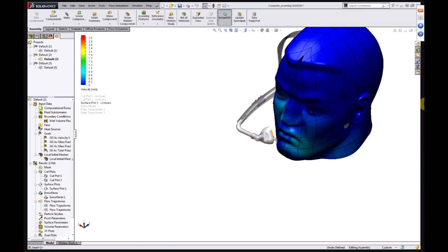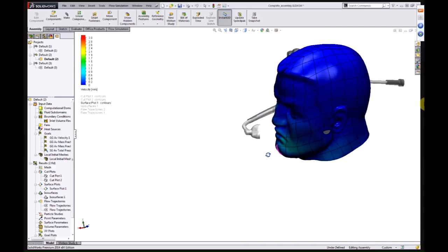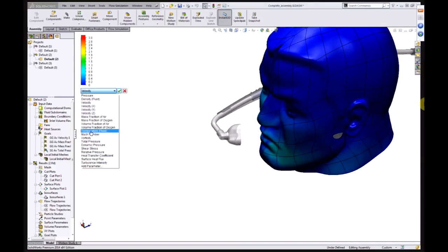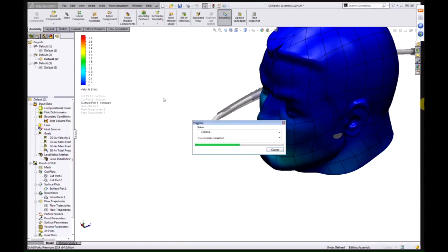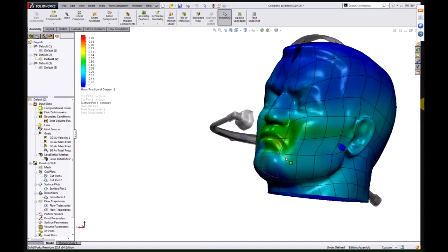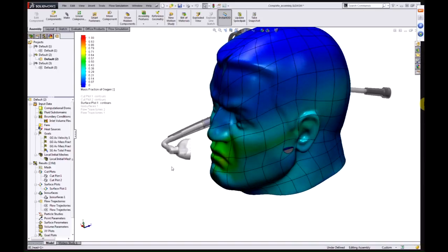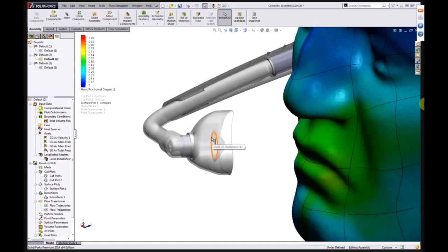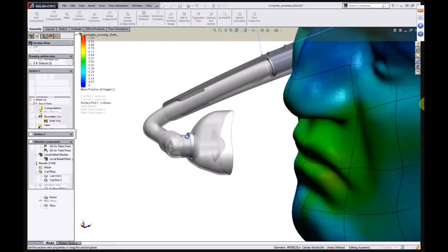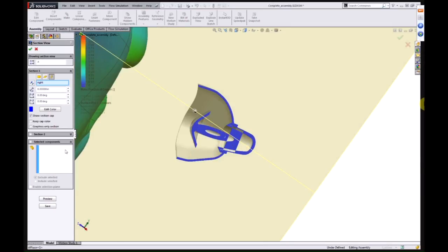The variety of things we can interrogate here. But we also have some design parameters available to us, particularly around the design of this little mushroom valve through here. Okay, we can adjust the angle of these arms, we can adjust the spacing, and because we're inside of SOLIDWORKS, there's nothing stopping us from finding the geometry we want to look at, double-clicking, identifying the dimensions, and changing them. As soon as we change something, it's ready to be analyzed. Because we're completely in sync with our CAD model. We would just change this value and hit solve.